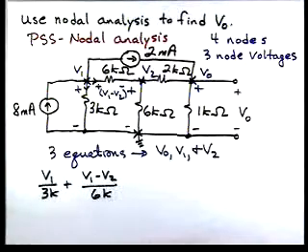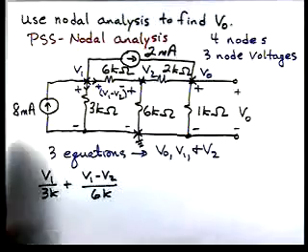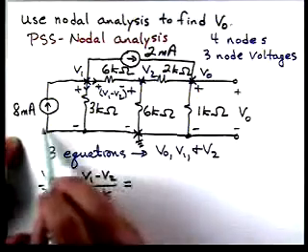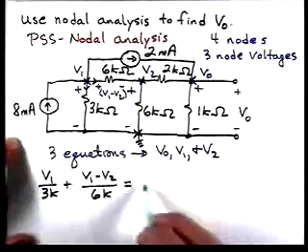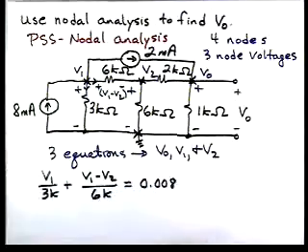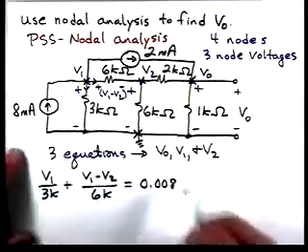And then there's the current leaving through resistances. Let's set equal to the sum of the currents entering from sources. So if we look over here, this one is entering. And then this one is leaving.